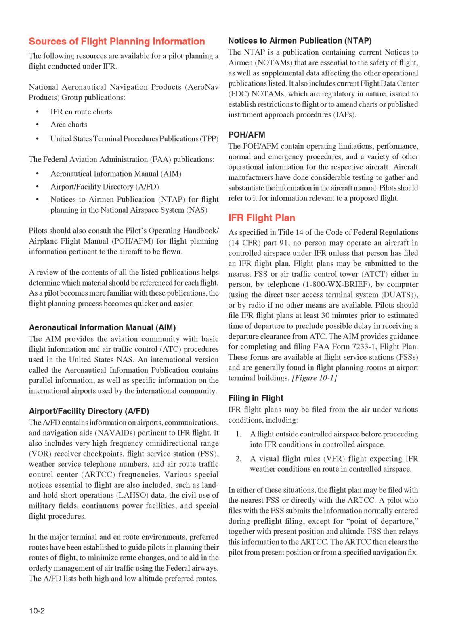Notices to Airmen Publication, NTAP. The NTAP is a publication containing current notices to airmen, NOTAMs, that are essential to the safety of flight, as well as supplemental data affecting the other operational publications listed. It also includes current Flight Data Center, FDC, NOTAMs, which are regulatory in nature, issued to establish restrictions to flight or to amend charts or published instrument approach procedures, IAPs.